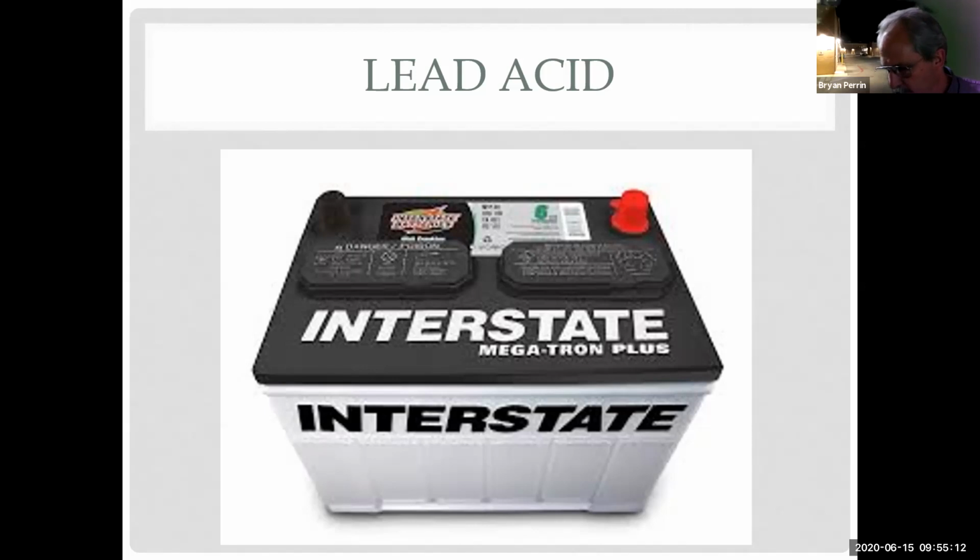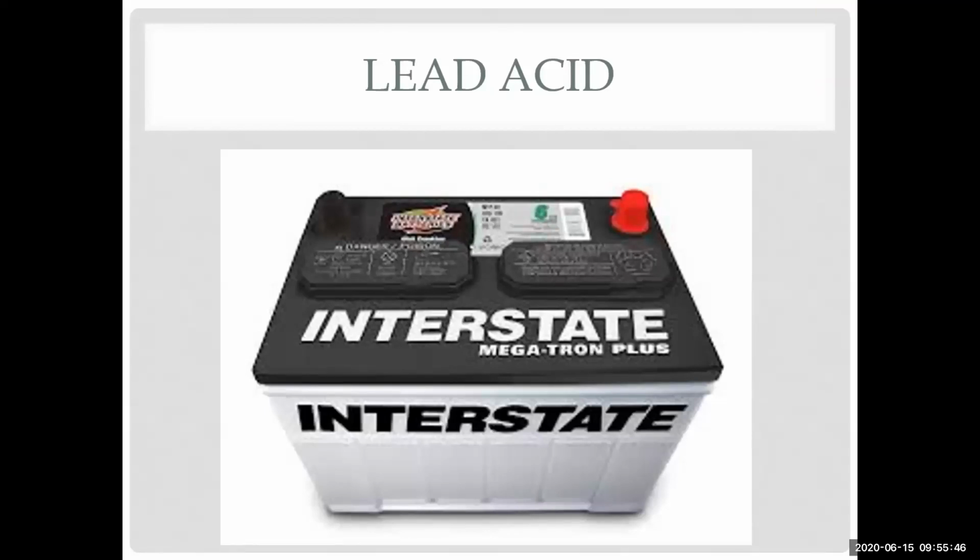So if I hook things in series, for example, I have AA batteries here. Each of these batteries is 1.5 volts. So if I take my positive to negative, I'm now wired in series. I now just made a 3 volt battery. If I put another one, it'd be 4.5 and so on. Has anyone ever opened up a 9 volt battery and looked inside? There are 6 cells inside here.